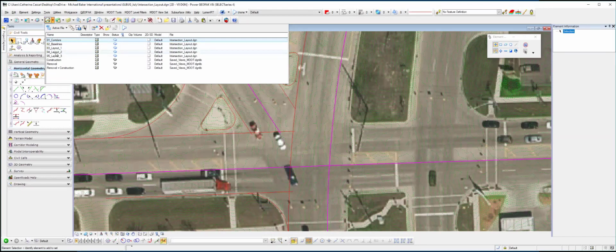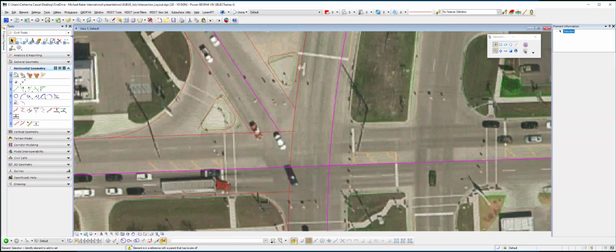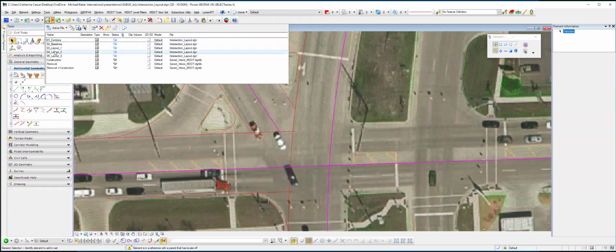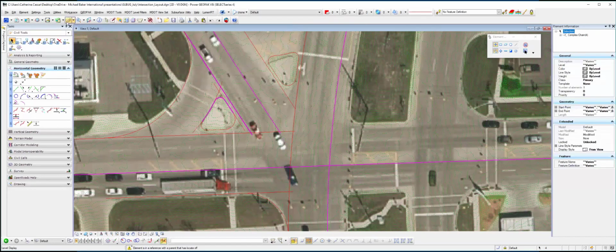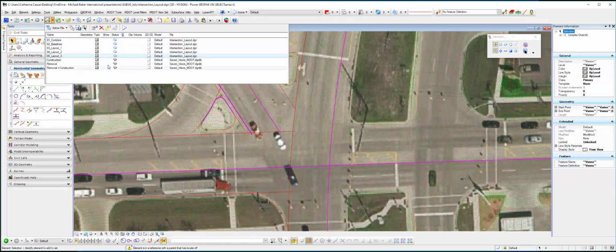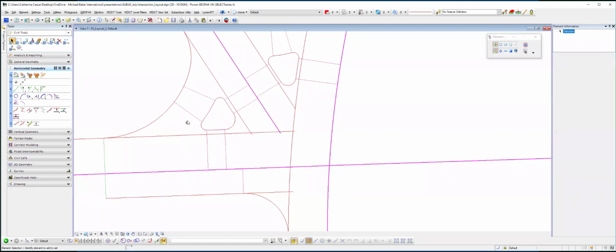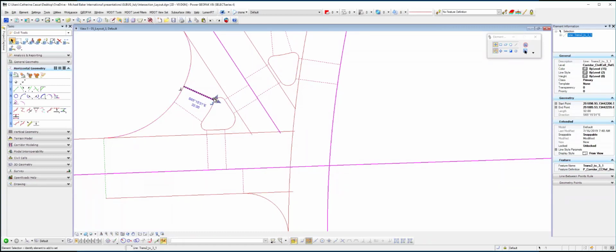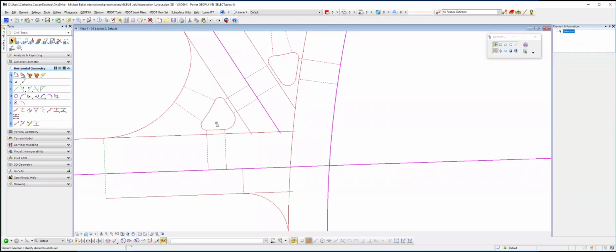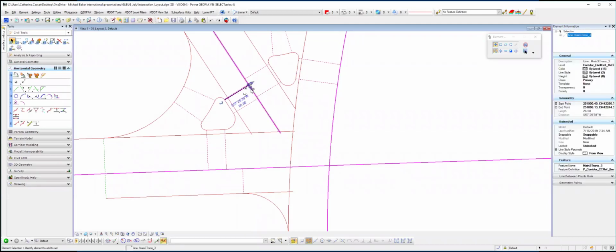And one of the other things is, the last thing is some control points, or some control lines in this case, that I find have been really helpful in the past. So in the case of these islands, knowing you're perpendicular to the end point or to the key point of that radius becomes really important when you're trying to control any warping that you may have to do inside of the pavement. So these are just perpendicular from the main line.